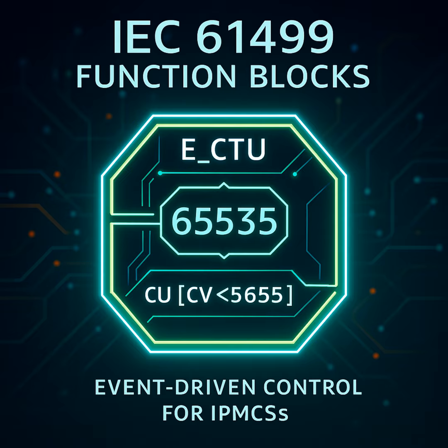Now, if you have a really fast event, maybe from a wheel speed sensor or some quick machine cycle, that pulse could arrive between PLC scans. And the PLC might miss it entirely or count it late. Could happen. You might get count jitter or lose counts altogether, especially if the scan time isn't fast enough or varies. Your count isn't truly tied to the event anymore. Which means if you're tracking something critical, like material flow or total cycles for maintenance schedules, your data could drift